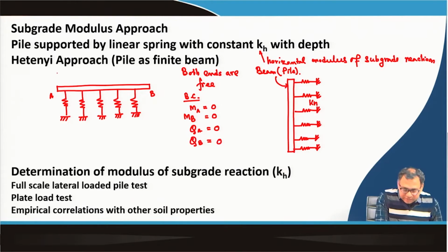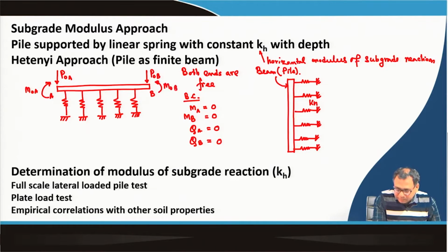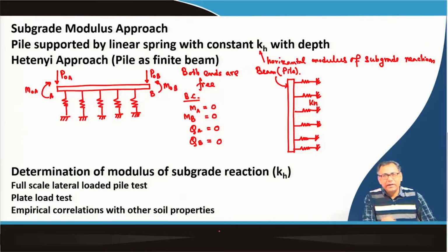So, that is why we have to apply these end conditioning forces P0A and M0A to make the net bending moment and shear force zero. Okay, that is the concept.